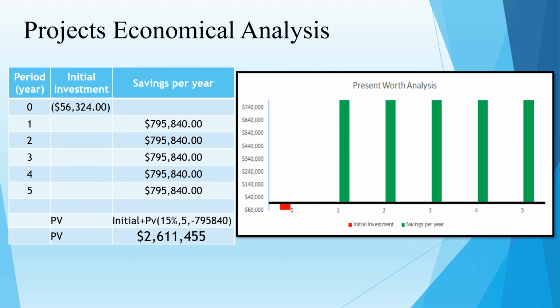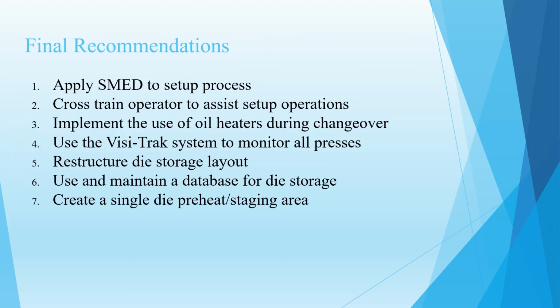Again, we want to say that this translates into an increase in production capacity by increasing machine availability by almost 3,000 hours a year. The present value of this project is worth $2.5 million. In conclusion, we recommend Cast-Rite adopt SMED principles into their setup process. Cross-training operators to assist in setup will allow them to reach that goal with minimal cost.